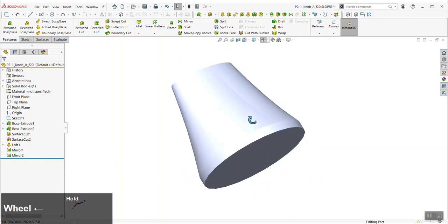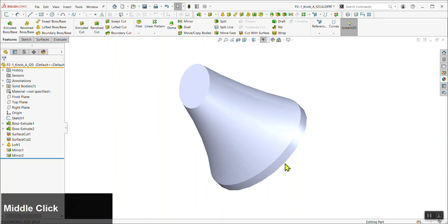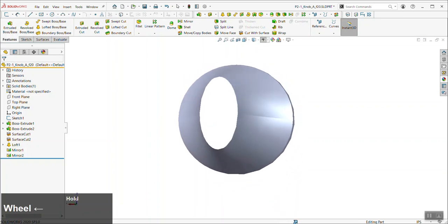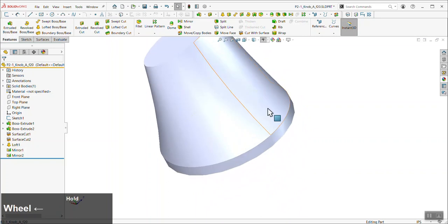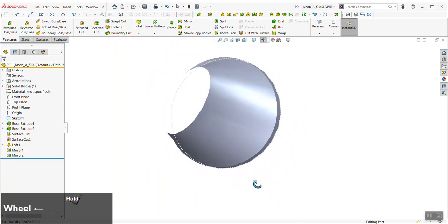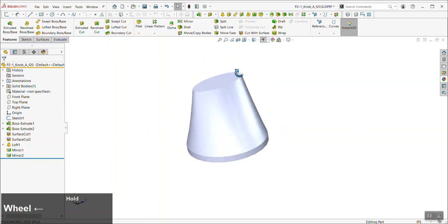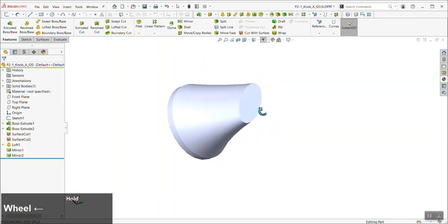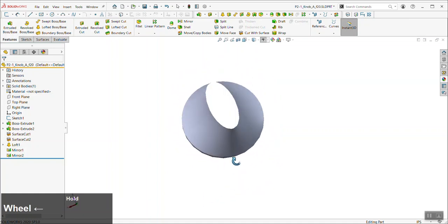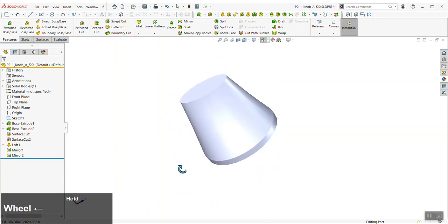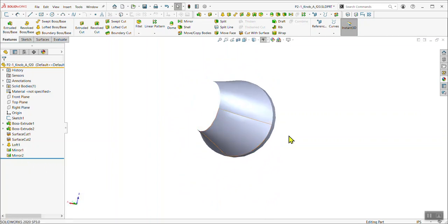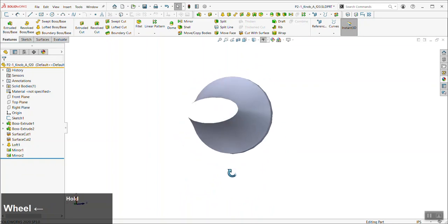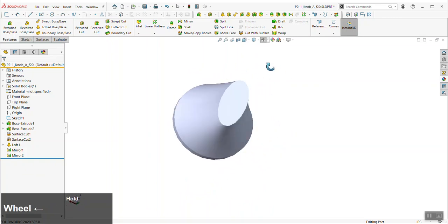And what you'll notice, hopefully, is that there is a seam on this file by using this method. Seams in SOLIDWORKS are not ideal. If this were to be molded, it would have a crease here. Maybe it's a design element, but often things like this are unintentional and not desired. The reason for this is because of the guide curve, we don't have a tangency set to it. So this is where it's important to be aware of other options we have.